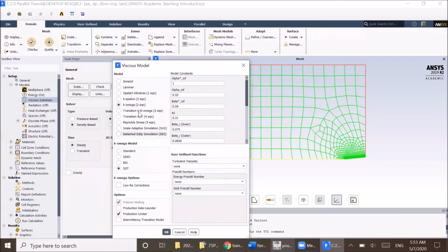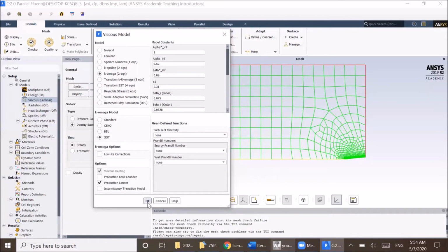You can research those options more thoroughly, but for me, what I've been using is either Spalart-Allmaras or K omega SST. Now I've noticed that Spalart-Allmaras works well for anything below Mach 2. The reason for that is this specific model was developed for Boeing for the transonic flow regime, since it's very specific for their cases. Another model that works fairly well and gives fairly accurate results is K omega SST. So I'm going to be using this one for this specific simulation.